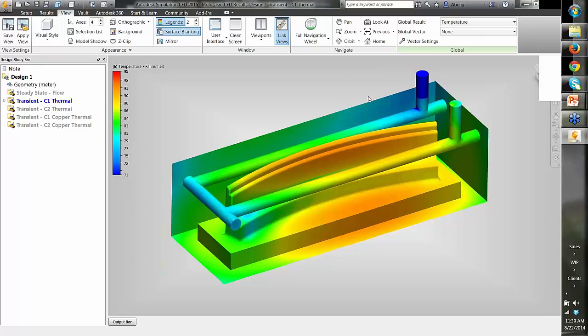One of them is that a lot of people didn't know how to use Moldflow, but they were tool designers. So they've done a lot of tool design, a lot of tool parameter tweaking, and have worked with Moldflow users. But when they start going from simple straight ladder channel systems to more conformal cooling channels, or really trying to dial in their tool set for high cycle performance, you can look at it strictly as a thermal problem.